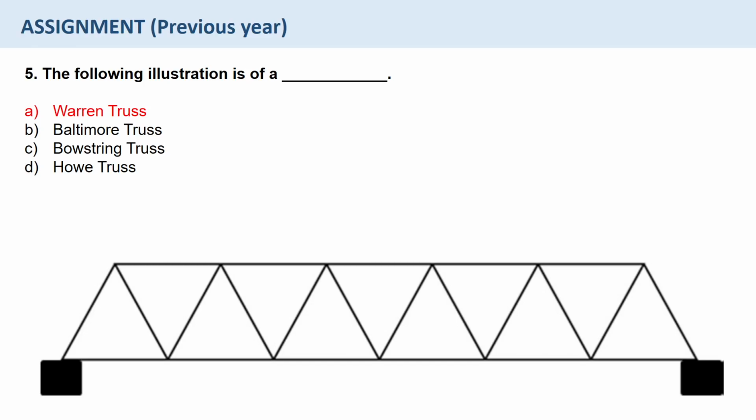They are, as explained in the previous question, assemblies of flat plates or slabs which can be inclined in different directions and joined along their longitudinal edges. They can be used in walls, staircases and roofs. This originated in the 1920s and became popular to construct roofs for industrial warehouses and public buildings. They are typically made of cast in situ or precast reinforced concrete or steel plates, and they are capable of carrying loads without the need for additional supporting beams along mutual edges.